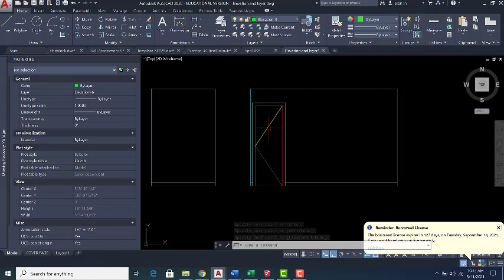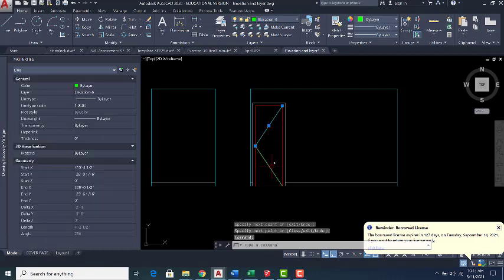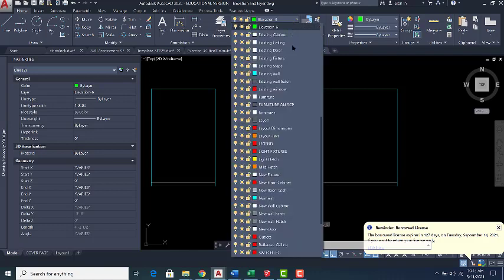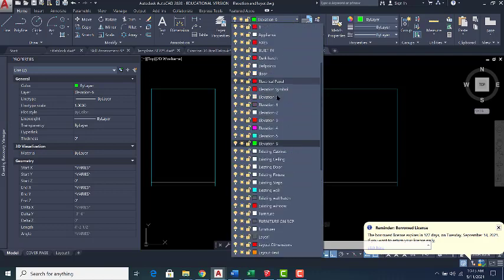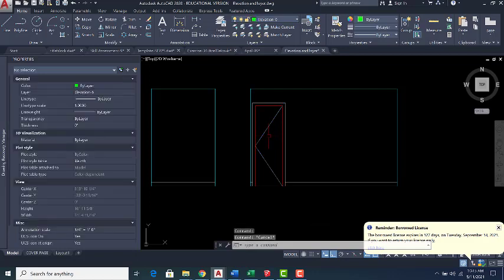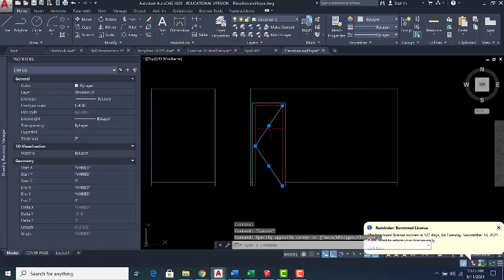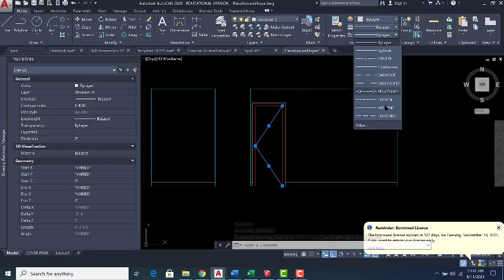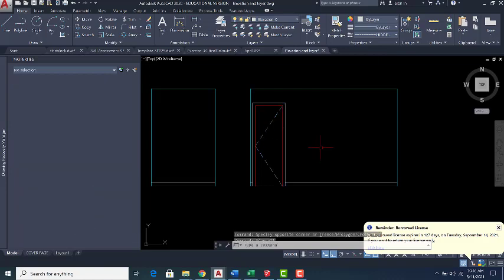And this is for sure a wrong layer. Again, it's a symbol. I would put it in the thinnest layer that I have. It's layer 0. And also, I wanted to show it as a hidden line. It's not an actual thing. So I would select them. Again, make sure you select the layer first. Then go here and put it in. Maybe this one. I like it. This is good. Hidden 2.